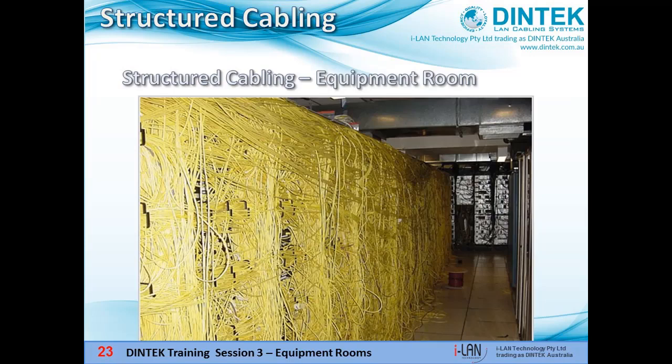Management panels are more than just cosmetic too. Untidy cables can increase signal interference and crosstalk due to improper placement of data and power cables. Cables can also get damaged due to improper bends, movement or sharp edges, or just from people tripping over it or trampling it. I've seen cabinet doors that can't be closed due to untidy cabling, which leaves the cables susceptible to damage by people jamming the cables in the door.